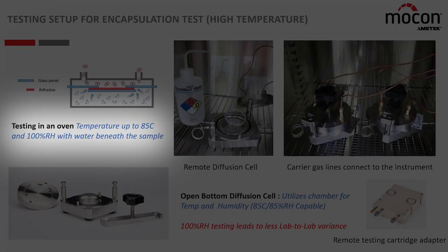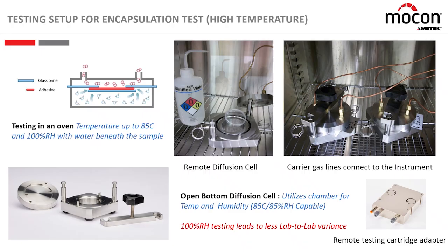I can put it in an oven, and I can increase it up to 85 C. I can run this test very well. Someone may ask, well, geez, if I have water in here and I'm increasing the temperature, aren't I pressurizing it underneath? I mean, that's what happens when you have water and you heat it, you're going to create some pressure. Well, the cell that we have here actually has these little coils, these little lines that allow the pressure to vent. So we're not pressurizing the sample.